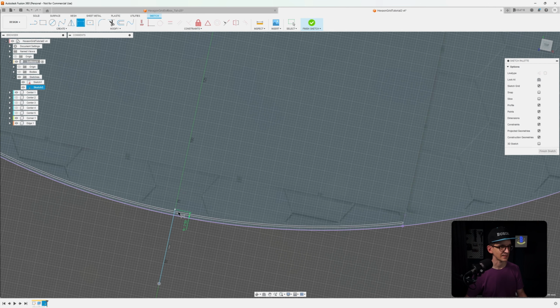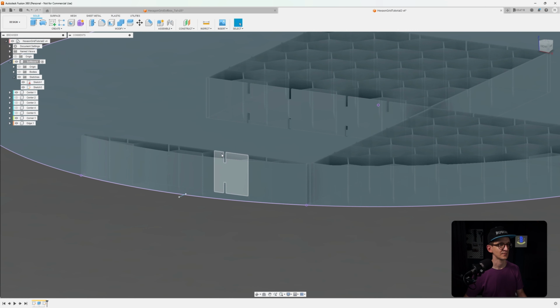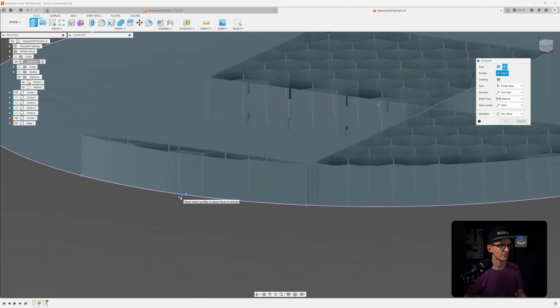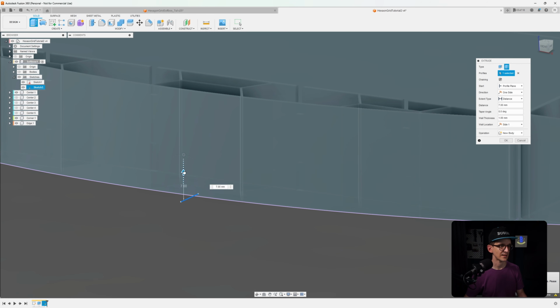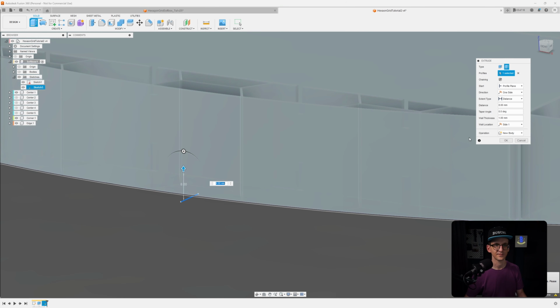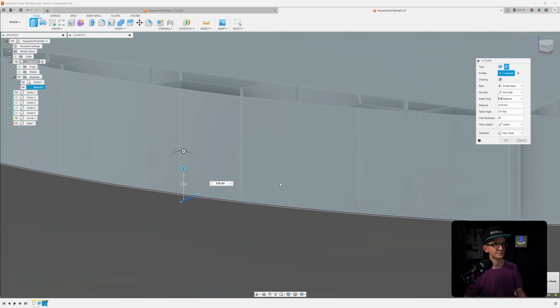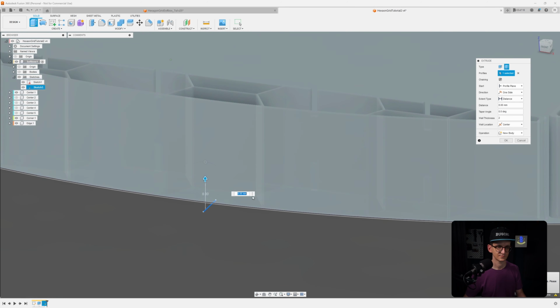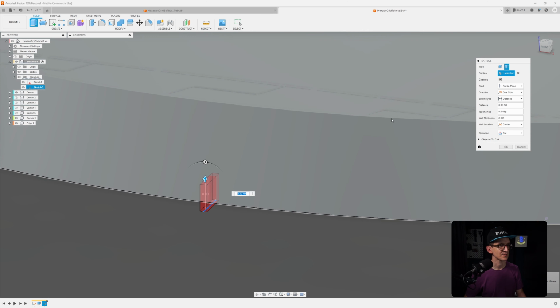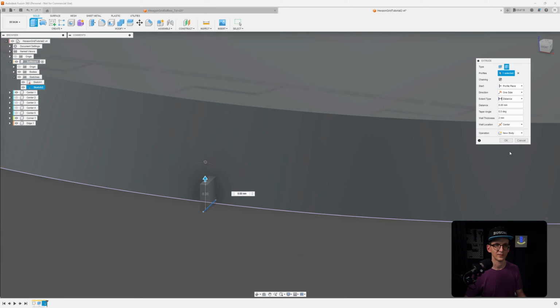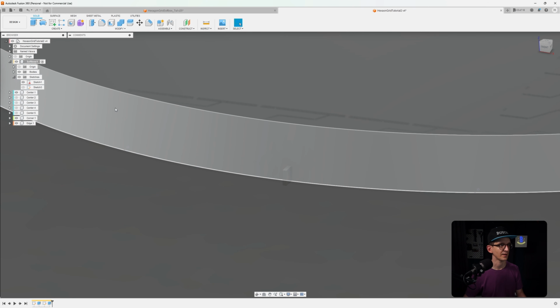And then the same, the overall, I don't know, something like 10 to have enough excess. And then we go to extrude and thin extrude once more. And we extrude this up by, again, 8. We create a new body. And actually we go from the center. And the wall thickness, again, will be 2. And the body is invisible. We create a new body and hit OK.